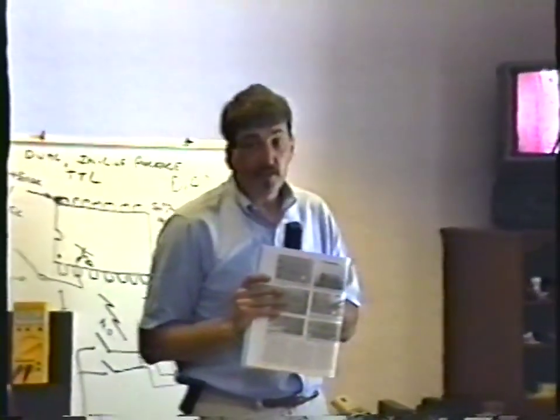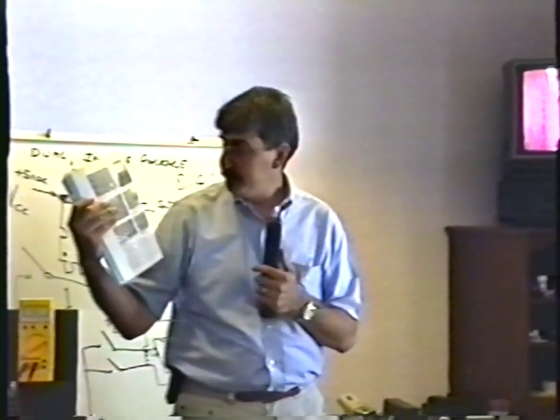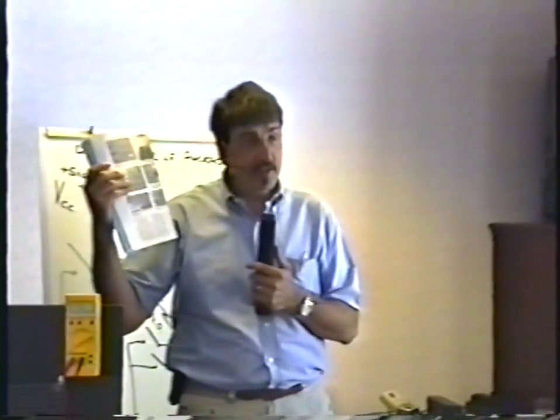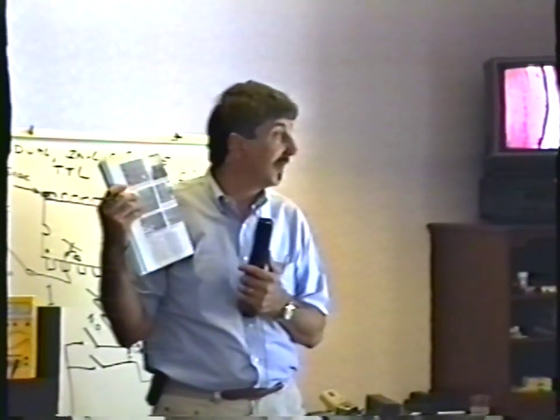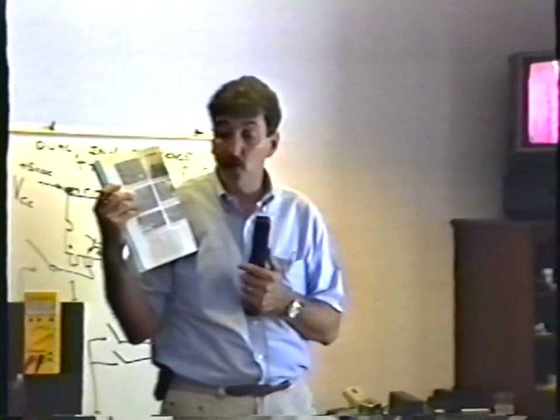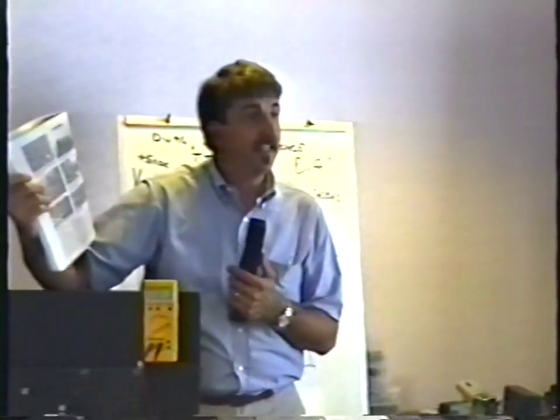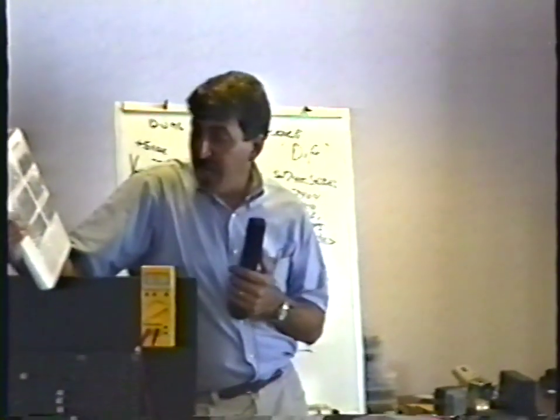To change the integrated circuit, we're on page 26 now. To change the integrated circuit, you're actually going to cut the integrated circuit off the board. Your main criteria when you change an IC is not to damage the board. That's the important thing. You don't want to damage the board. It's really easy to damage the board. You've already determined that the IC is bad. So you cut the IC off.